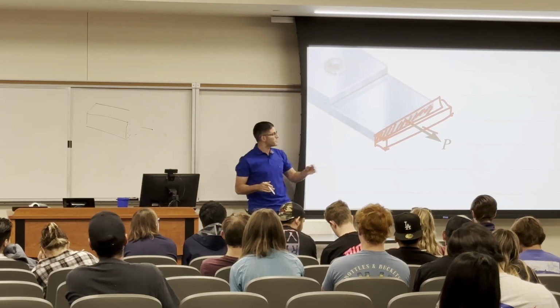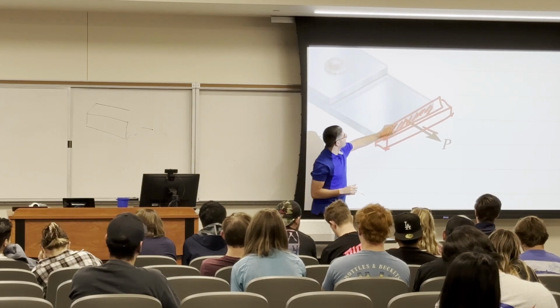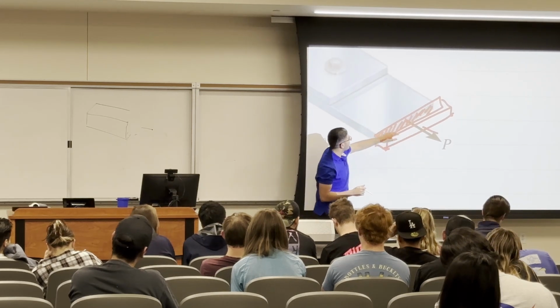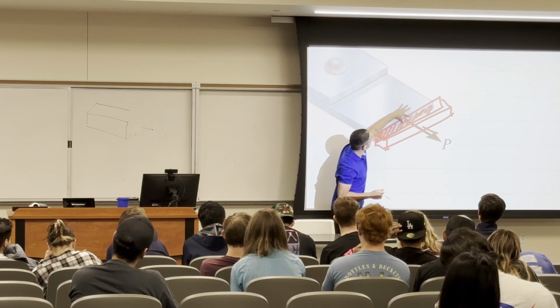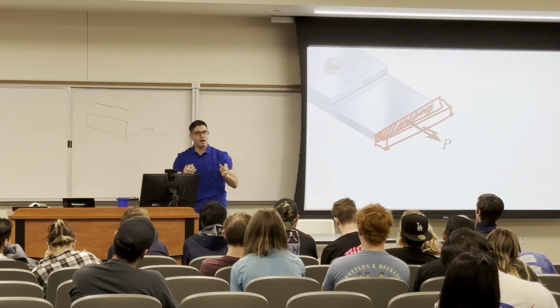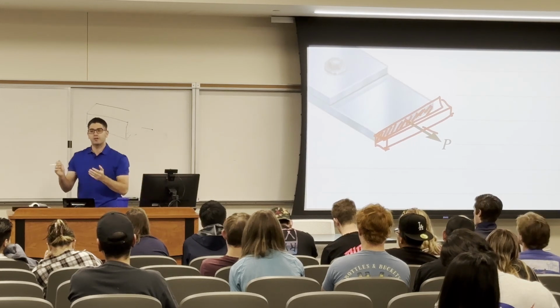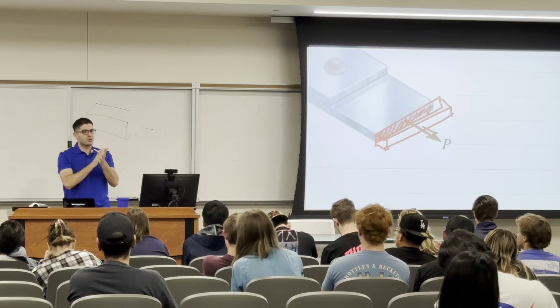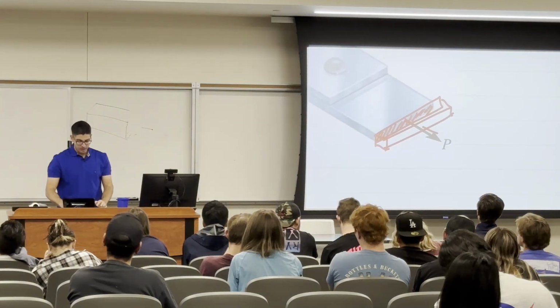In real life, if you see someone putting a point load, it will take time until the whole section is going to feel the point load. At least in the beginning, a small area is going to work, and it's going to expand until the whole cross section works. I'm explaining to you how the point load works, but in this class we're not interested in point loads. We're more interested in how this load is going to be distributed over the whole area.